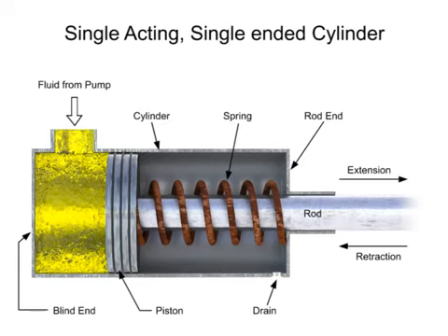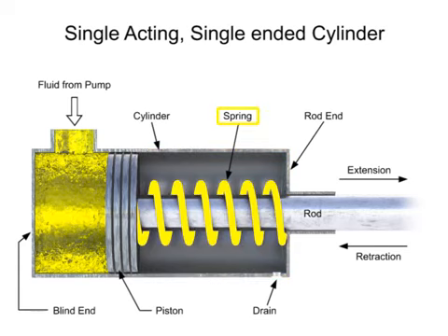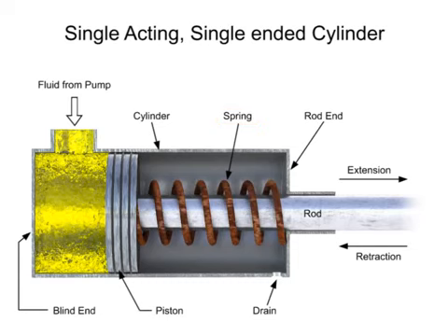A single-acting cylinder is a cylinder in which the working fluid acts on only one side of the piston. The other side of the cylinder utilizes a mechanical load, springs, compressed air, other cylinders, or the momentum of a flywheel to push the piston back in the other direction. This particular cylinder utilizes a spring on the non-fluid side. A single-acting cylinder produces linear motion in one direction.